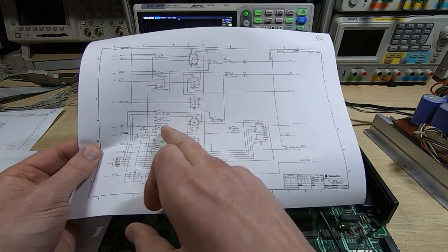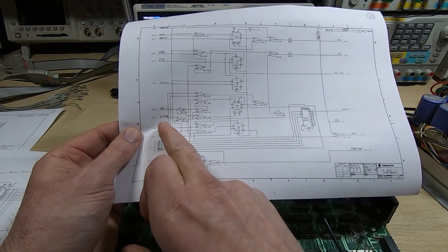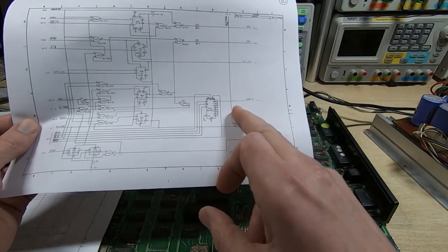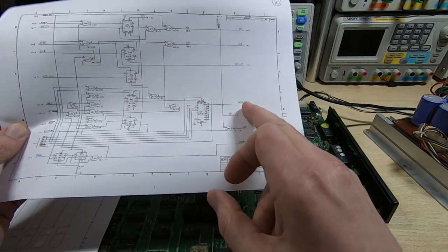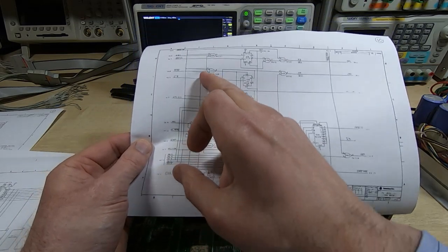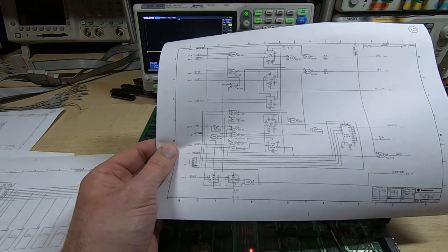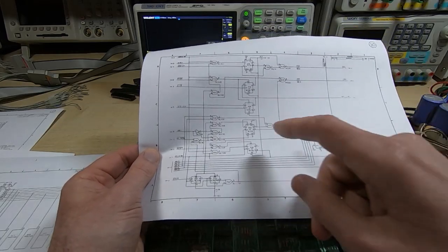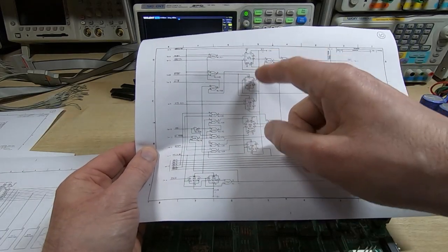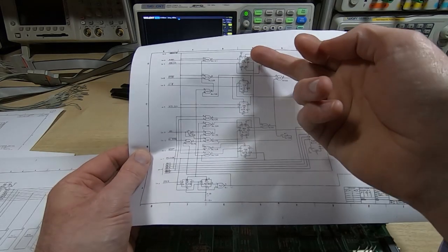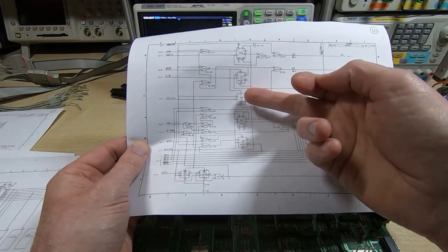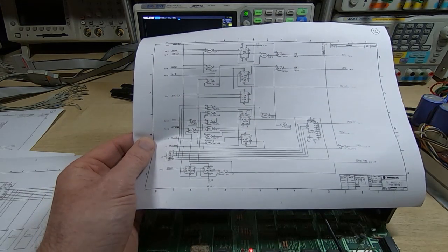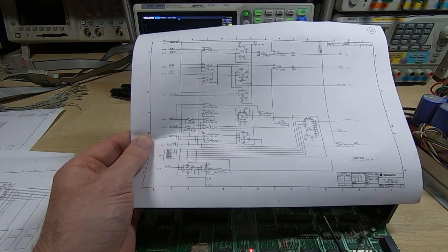So either there's an issue with the decoding to select the DRAM, so we've got the decoding here to select the EEPROM, we know that's working, but there's something amiss here, or the signal further back is not being driven as it should be. I suspect the problem's in here somewhere, so I'll start working my way through this. All I'm going to do is check each of the relevant devices that are in this particular signal path and see where the signal is getting lost.